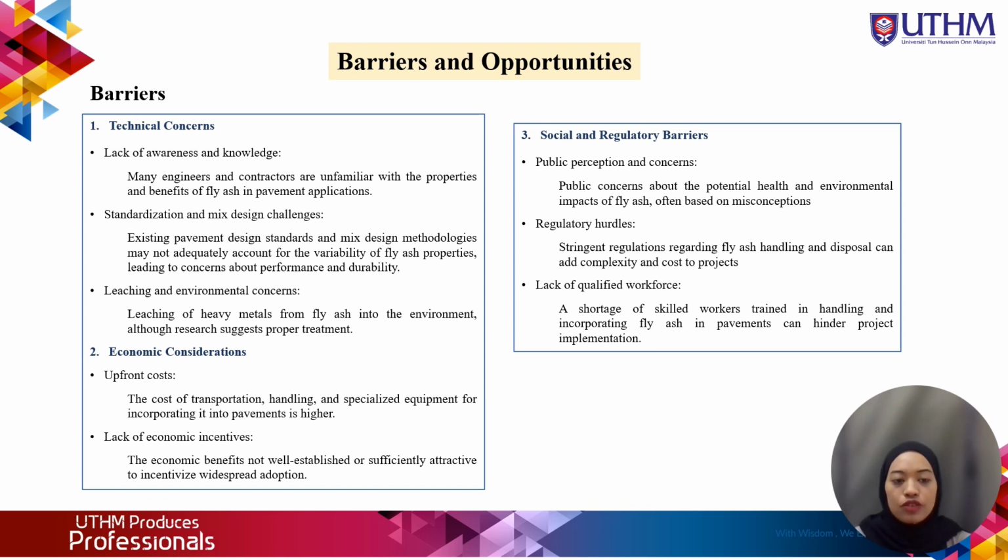For the barriers, the first one is technical concerns, lack of awareness and knowledge, which many engineers and contractors are unfamiliar with the properties and benefits of fly ash in pavement applications. Next is standardization and mix design challenges, which the existing pavement design standards and mix design considerations may not adequately account for the variability of fly ash properties. Next is leaching and environmental concerns, which is leaching of heavy metals from fly ash into the environment, although researchers suggest proper treatments.